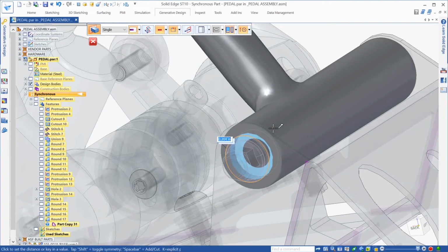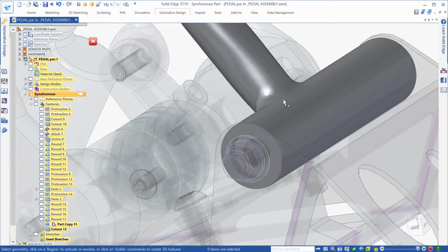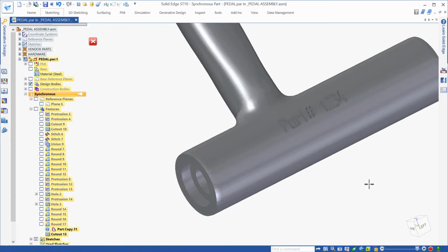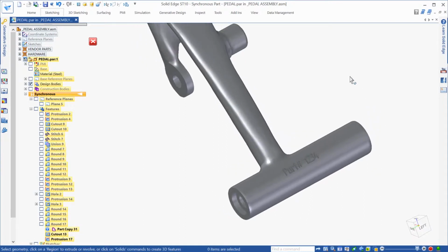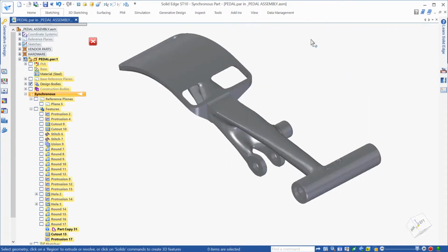For example, a cutout can be added to the lower boss for the purpose of placing a bushing. The use of standard modelling tools makes this process quick and easy by picking up on background parts in the assembly. We'll also add some geometry too. In this case, we'll add the part number to our part by first placing text, then extruding that text into the design. The power of Siemens convergent modelling techniques available in Solid Edge provide an engineer with the ability to further the design of mesh models fast and easy.